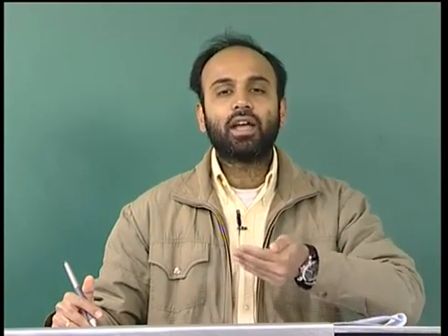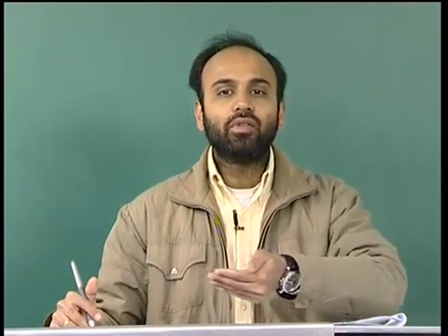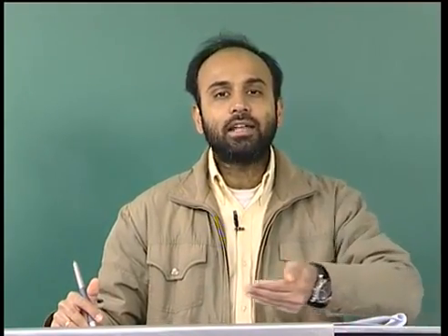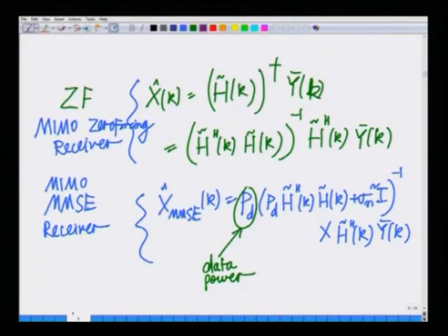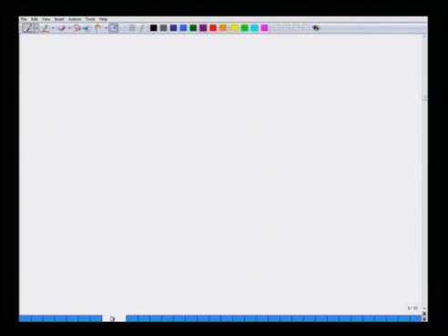I compute the n point FFT, that gives me the uvth elements of the channel matrices across all the n subcarriers, all right, and then you do that for each element of the MIMO FIR taps and construct the channel matrix across each subcarrier. We can use this channel matrix in the procedure that we have described before to employ either zero forcing MIMO detection or minimum mean squared error MIMO detection, and that completes the MIMO OFDM communication system. All right, so that completes our discussion on MIMO OFDM.